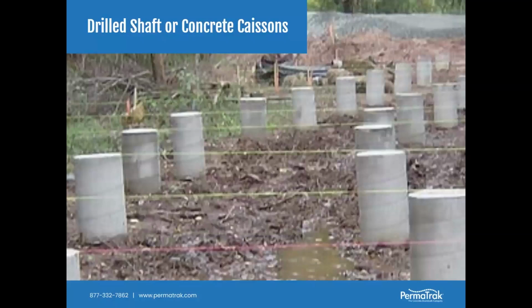And drill shafts, like I said, in the southeastern, or south central, part of the U.S. have been very common. A drill shaft is nothing more than augering a hole to some prescribed or design depth, and then either casing or uncasing the hole to keep it open, and then placing a rebar cage of steel, and then filling that void with concrete and extending it up above the grade to some elevation that's needed for the boardwalk. So a good long-term solution, and may in fact be required in some situations.